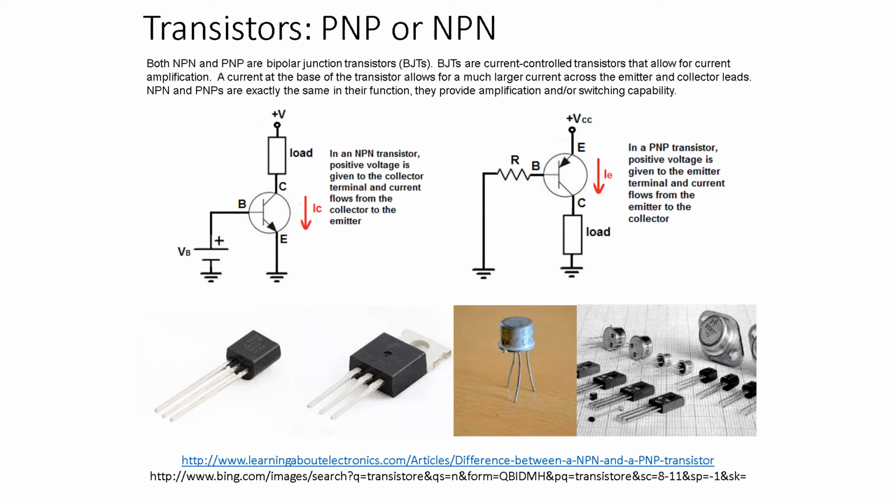One of them's the base, one of them's the collector, and one of them's the emitter. And essentially what they do is they allow for an amplification of current going through them. Essentially, you can use them to do some very basic audio amplification. Even more general use for them is actually using them as electronic push buttons, which is an interesting way too.